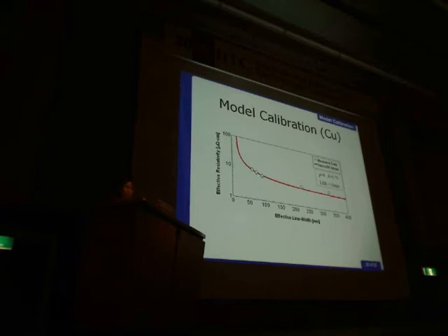So now we can say that we have not only found a closed form model that includes LER, but we have calibrated it to real data. It may not be the best data, but it still shows exactly what's going on, especially below 100 nanometers. So here's the limit we're talking about, as line width approaches LER equals 14 nanometers. If I try to use the same process to manufacture something down to 14 nanometers, I should expect a very low